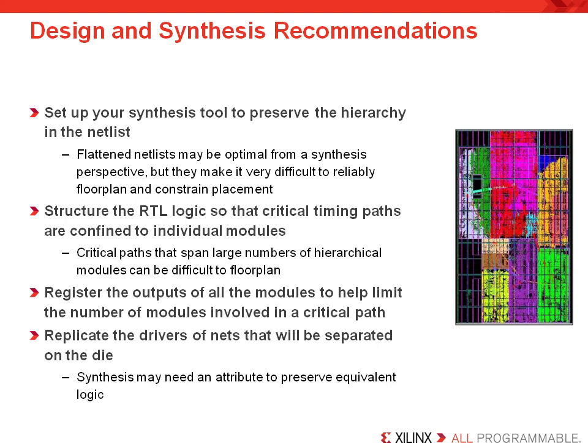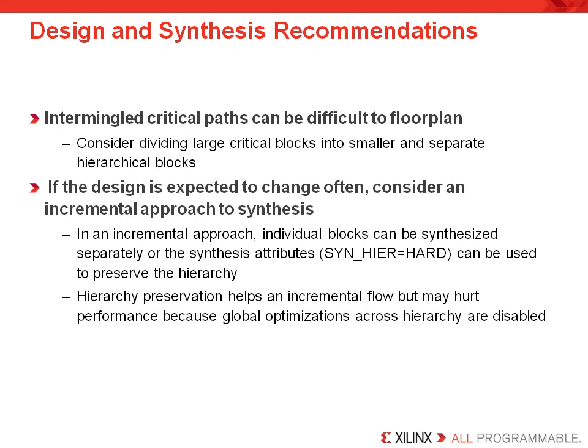Try to register the outputs of all modules. This will help limit the number of modules involved in a critical path. You can also opt to replicate the drivers of nets that will be separated on the die. Synthesis may need an attribute to preserve logically equivalent logic. There may be some intermingled critical paths which can be very difficult to floor plan. You may consider dividing large critical blocks into smaller ones, and this will make it easier to isolate blocks.